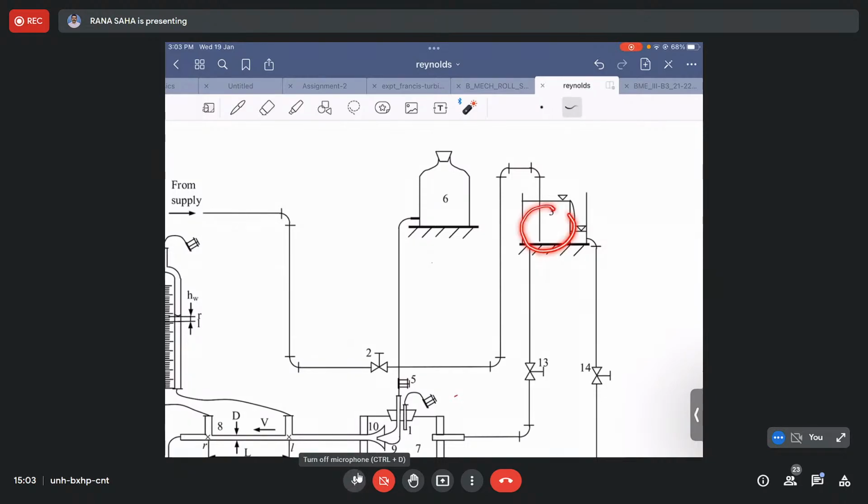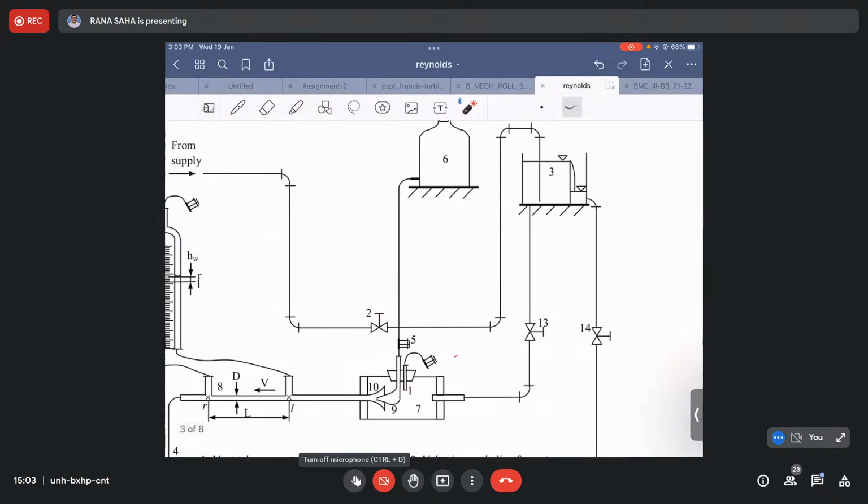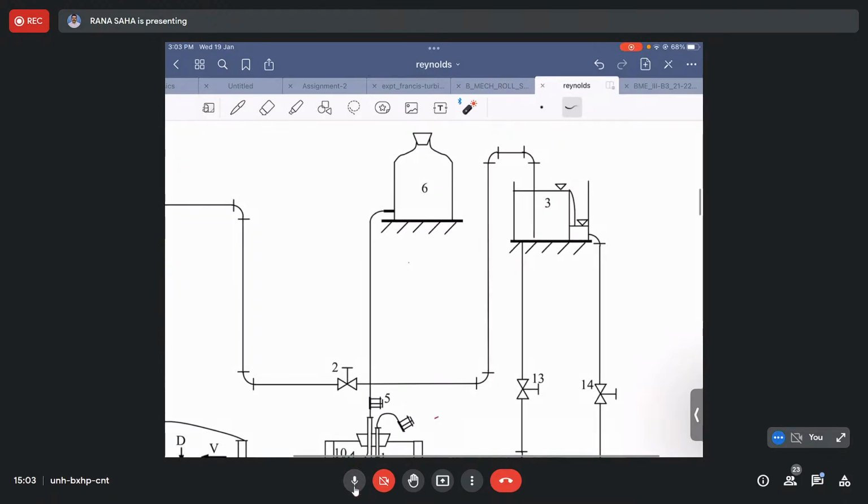This part, when you see that water is coming up through the drain line from this tank, we can say that yes, it is ensured that the tank, the usable part of the tank for the experiment, is now at constant head. Okay. So that actually is the starting point. That should be the starting point of the experiment.